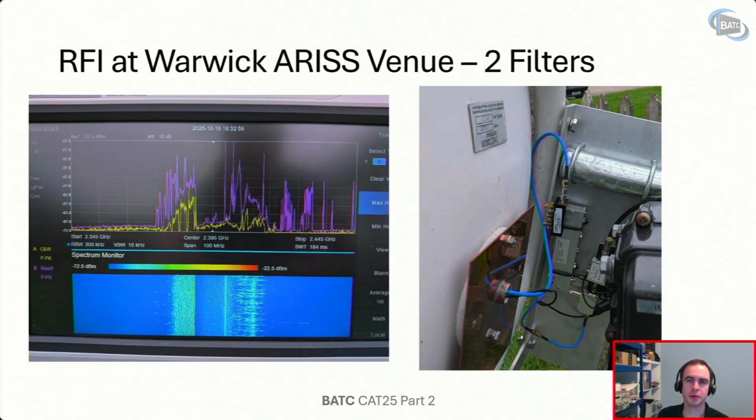On the right there, you can see the photo of the setup. So the blue cable is coming out through the boss of the dish from the LNA that's at the prime focus. It's then going into a 3 dB attenuator. This is to provide a good return loss, as Jen talked about, for stability for the LNA. I was a little worried this much power going into the blocking of the filter wasn't going to provide a good impedance match to the LNA. So I've got a 3 dB pad in there, then the first filter, then the second filter, and then that loops around into more amplification to bring it up to the right level for the mini tuner input.